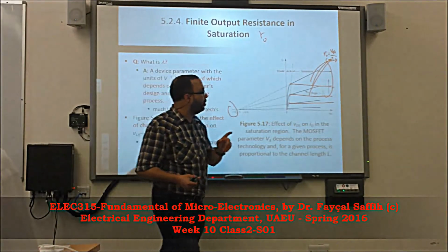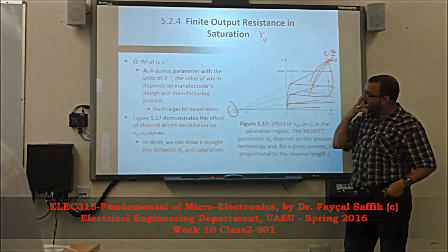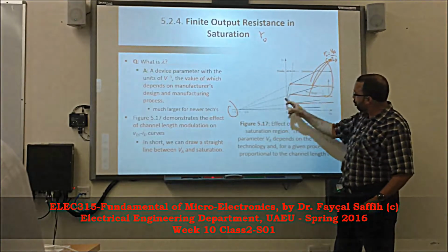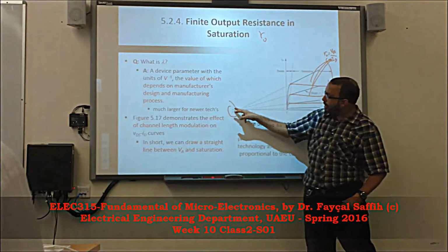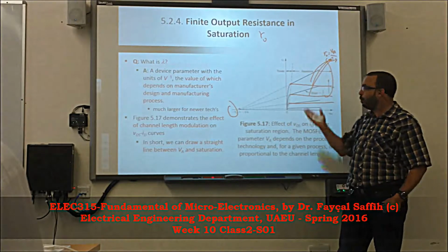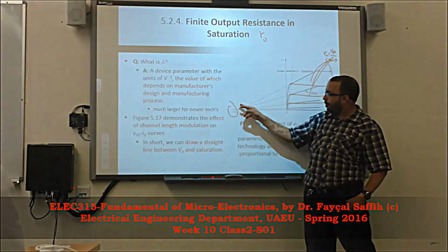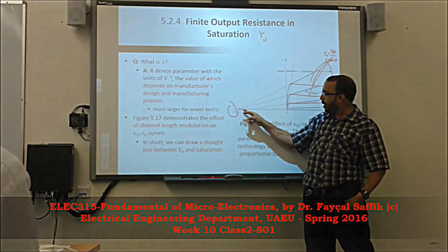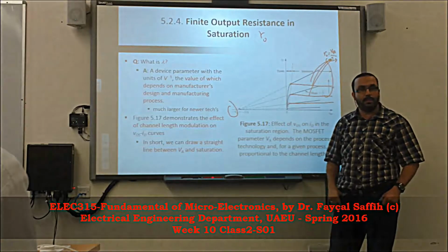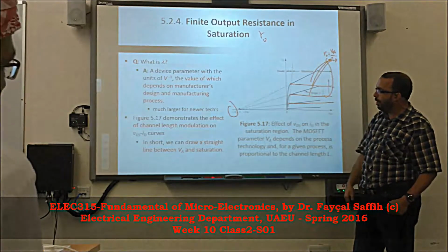And now we come back to the graph again. This is now the real MOSFET, or the closest to the real. If you take the lines here, they all intersect at a single point. And that's what Mr. Early found. When he tried to extend the lines all together, he found them intersecting the VDS axis at the same point. Then he started to ask himself why, and he found the early effect.